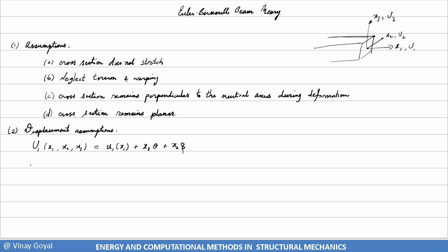And the next thing is x2, in the x2 direction, out of plane of this page. We're going to assume there's no deflection. So this beam does not deflect out of the page, only axially and in the x3 direction. Refer to this figure on the top right to figure that out. U3, we're going to assume that's equal to small u3 with respect to x1. So with that said, let's now study what is going on with this beam. I'll draw the beam in the deformed configuration.